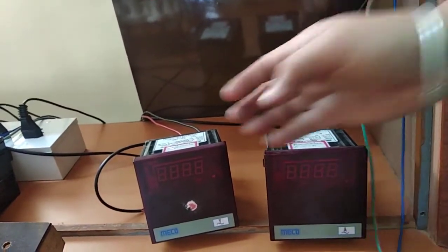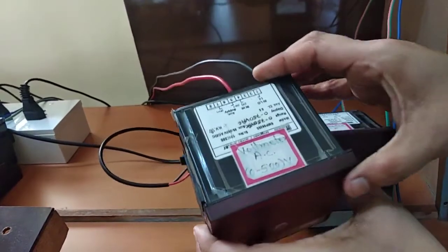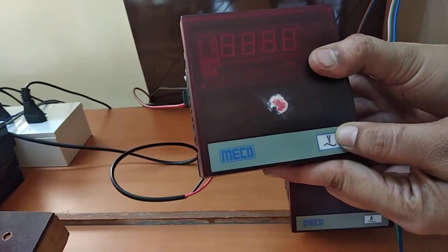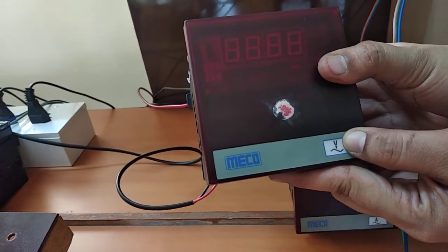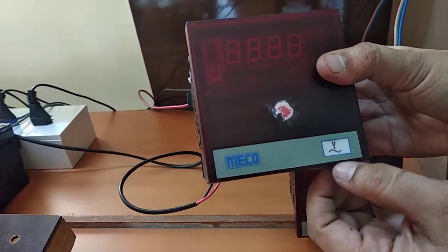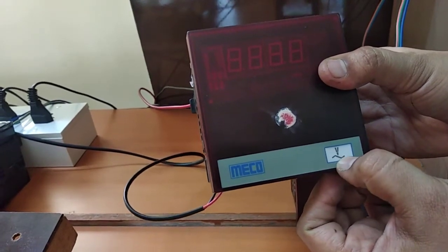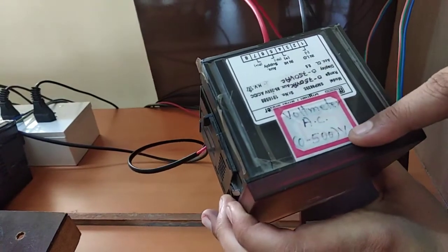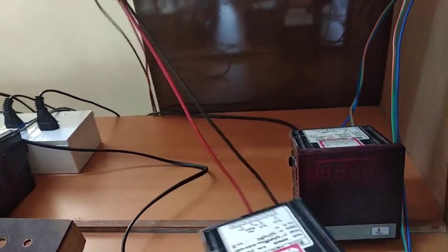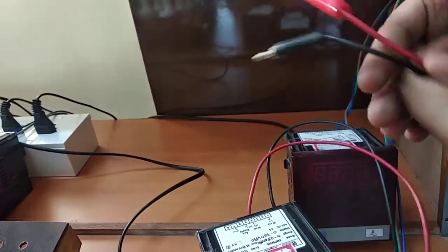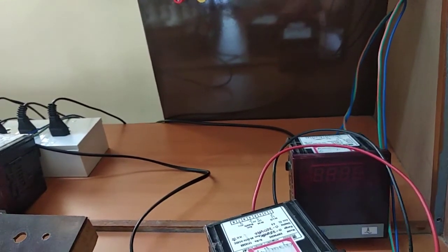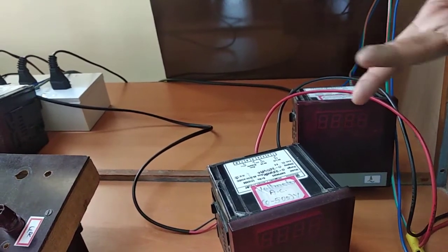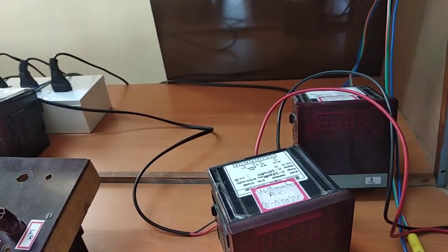All right. Next, let us learn about a voltmeter. This is an AC voltmeter. Voltage is measured in volts. The unit of voltage is volts, right? And AC is indicated by this line. And this voltmeter is of the range 0 to 500 volts. And then this voltmeter has 2 terminals. In AC, the polarity of the leads does not matter because the polarity keeps changing with every cycle of the frequency.